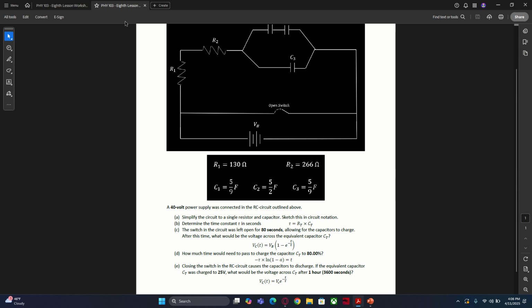The negative sign is there. It just looks like it's part of the division sign for the t over tau. But alright, that's good. So 1 minus e raised to the negative t over tau, where t is the amount of time that our capacitor has been storing charge, and tau is the time constant.